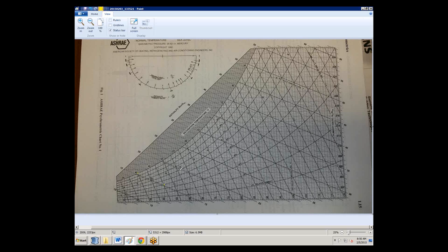So we're looking at this region as wanting to make sure anywhere in here we're getting very accurate wet bulb readings. The other thing we use it for is determining whether or not the return air stream has more or less enthalpy than the outside air stream. In the cooling season, we want to use the source with the lowest enthalpy. Rather than using just the enthalpy numbers, which are less easy to understand for somebody out in the field, we want to use something more like the wet bulb temperature, since those are parallel lines here on the psych chart.